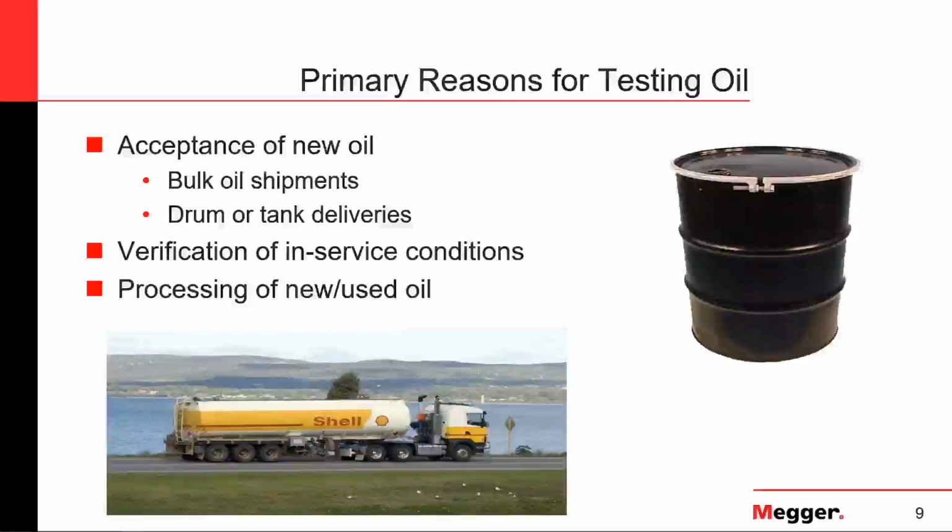Again, we need to make sure that the oil is still in good condition, that it does not have any important contaminants, or hasn't suffered any degradation that will affect the overall performance of the unit.